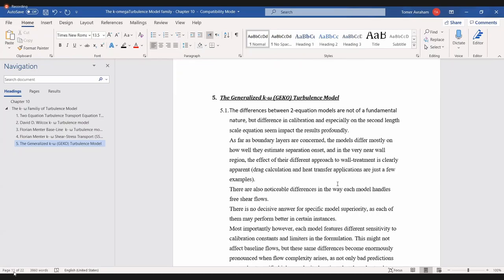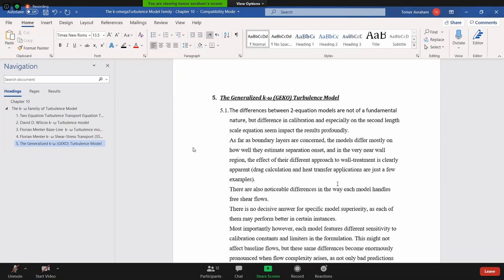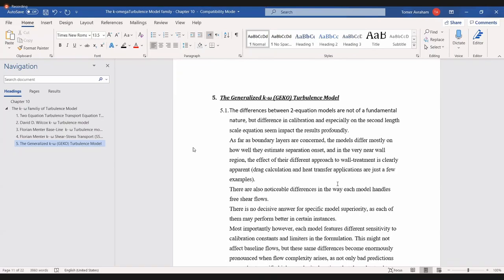If you go to the Stanford Center for Turbulence Research, they still investigate the kinds of transition they have, or in KTH, the oblique transition, the kind of transitions that you get from Klebanoff modes, except for one kind of transition, which is considered modal transition, which you can get from the Orr-Sommerfeld equations, the Tollmien-Schlichting waves that everybody knows.